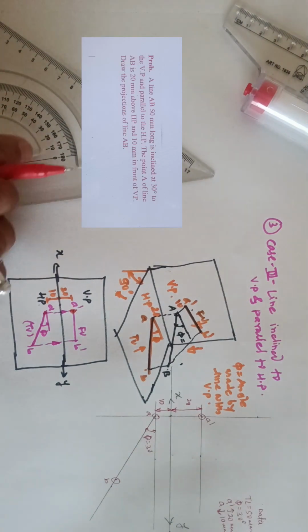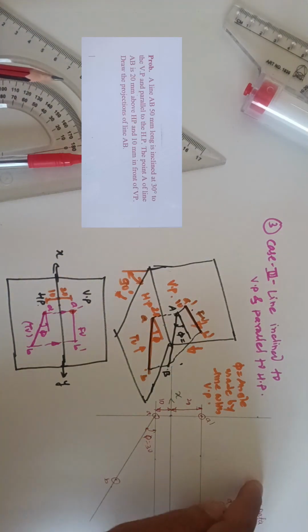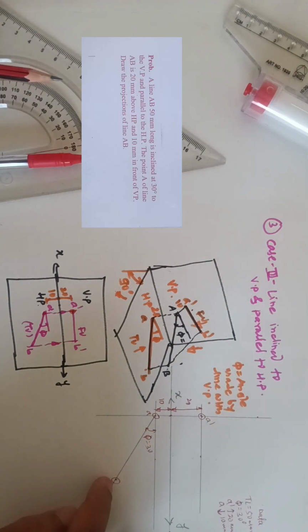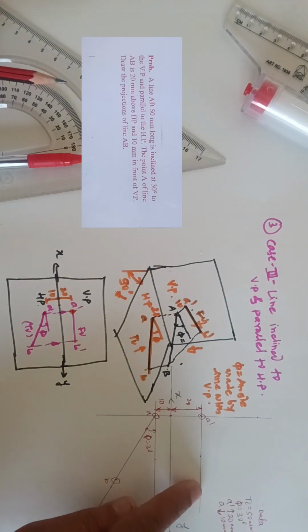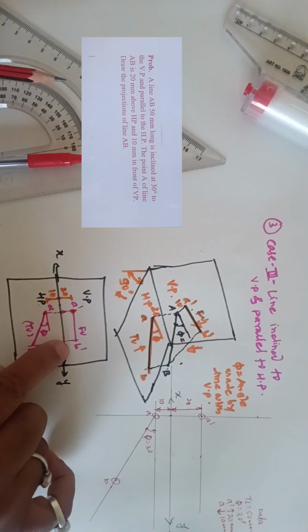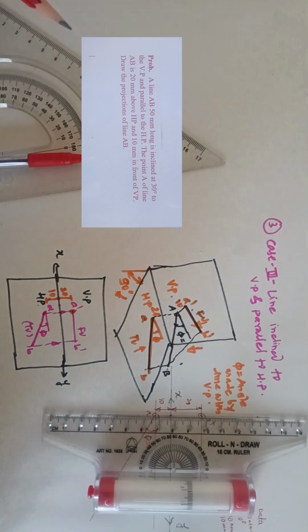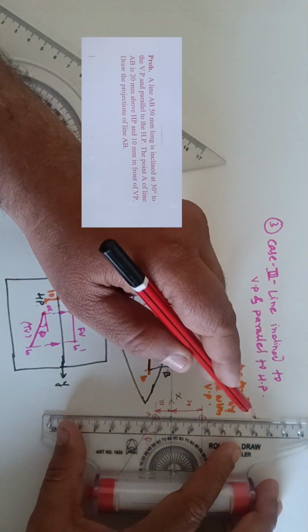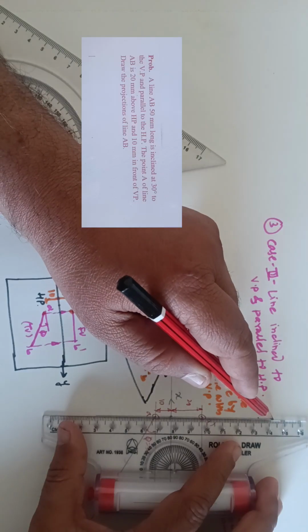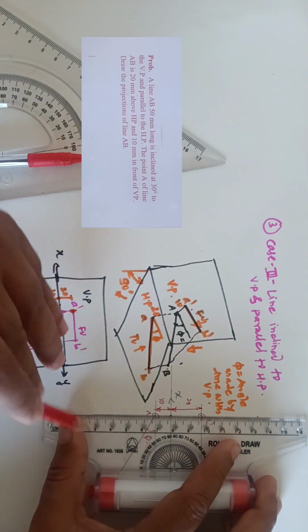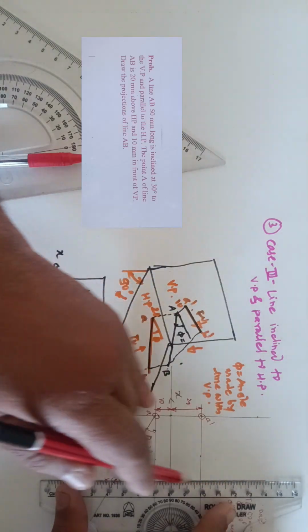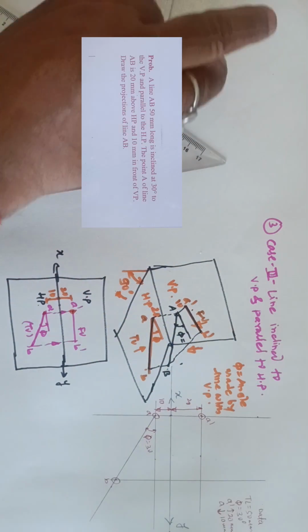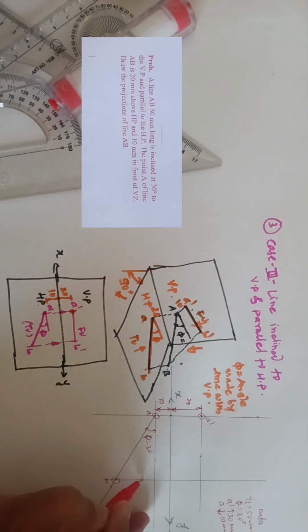Now the next procedure is that I draw the vertical projector, parallel to the original vertical line, from that point B, and it cuts the line which is passing through the front view A dash at one point. That point is nothing but the end point of our EL. So I have drawn this projector, here I show the arrow.